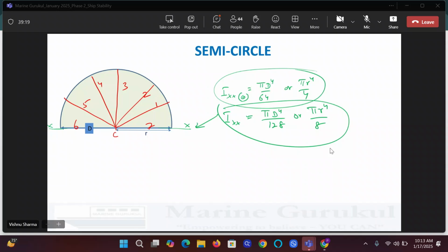It will be on three. Why? Because three is perpendicular. You have one quadrant on this side and the same quadrant on the other side. So the geometric center will be somewhere on this. Where will be the geometric center of a semicircle? It will be on the radius perpendicular to its diameter. It lies somewhere closer to the diameter.